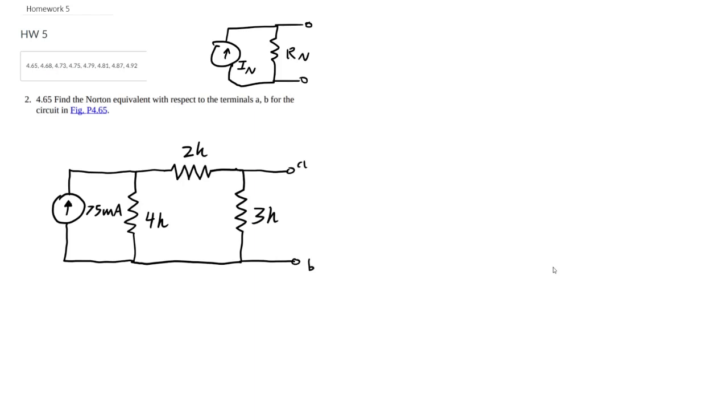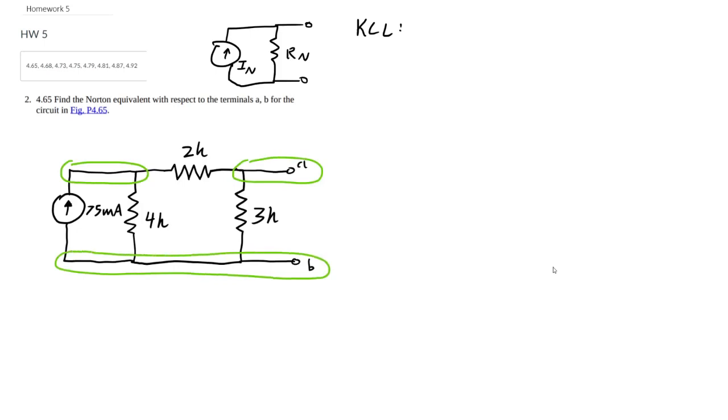So we're going to start with our universal method, KCL, and equations for components. Well, first thing we're going to do is label the circuit. Almost forgot. So we have V1, V2. I'm going to call this ground. I'm going to call this I1, I2, and I3.